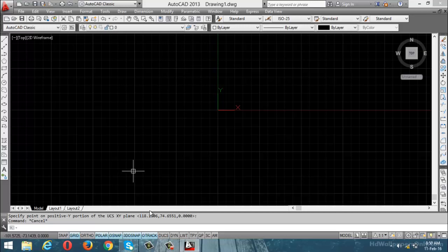Now we can select how many points: origin point, x direction point, y direction point. So UCS is also known as 3 point UCS, 3 point coordinate system. Okay, that is the process. That is the UCS setting, UCS process. Then after creation of UCS is complete.